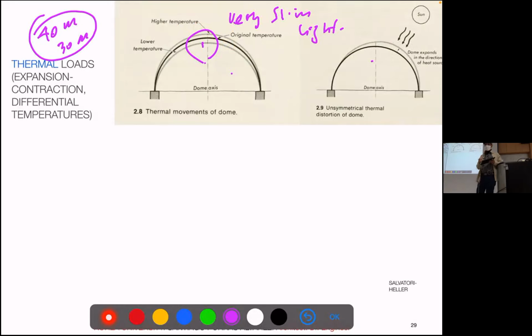And most important are asymmetrical or unsymmetrical loads. We always calculate symmetrical structures as symmetrical. And usually they collapse because of this asymmetrical thing. Imagine we have sunshine in the morning and the wind from the other side, a west wind. We have an accumulation of asymmetrical loads which may make the structure collapse. Maybe this is behind Malaysia and other structure collapses we saw before.